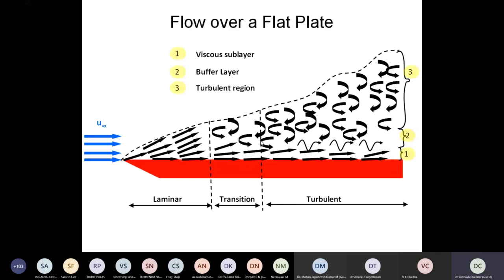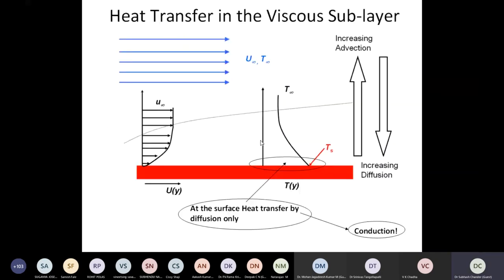So it's very close to the surface. Many layers are packed together, and the heat transfer is by diffusion, right? Diffusion heat transfer means conduction is there, right? You must be knowing that when we talk about the film coefficient, basically we are representing the conductance of this particular film which is formed. So this film should be very, very thin, so that it offers a minimum of resistance.